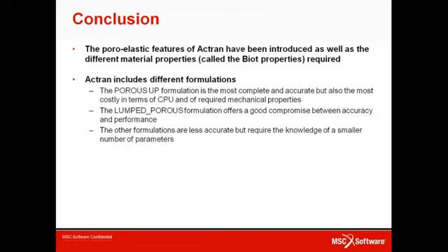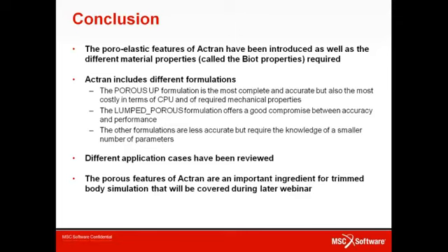On the other hand, we also have the lumped Porous formulation that offers a good compromise between accuracy and performance, and that is very suitable for a vast majority of applications. The other formulations are often less accurate, but have the advantage of requiring the knowledge of a smaller number of parameters. So we have reviewed different application cases, including some validations with experiments. And it is important for you to remember that the poro-elastic material library is really a key ingredient to handle more complex problems that are trim body simulations.